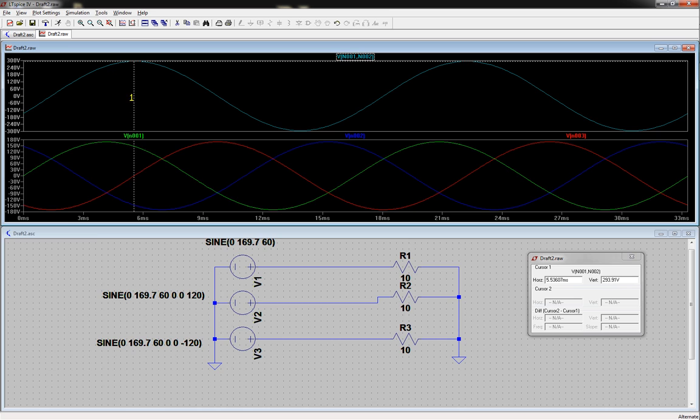Yeah, we're going to have the 292 or whatever, which is the peak value, which is the square root of 2 times 208. And to prove that, I'm going to show you how to alter these so you can pull them to where their peak values are the RMS values. If you want, it's kind of a way of cheating.